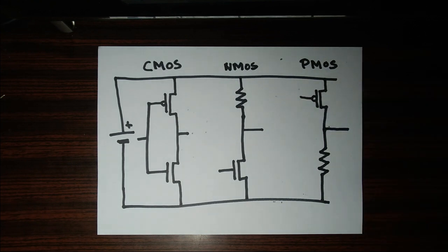Besides the disadvantages, NMOS and PMOS have a few advantages. One of these is that they require exactly half the amount of transistors of CMOS. Also, with NMOS, we can create a quick and dirty voltage shifter. This might be beneficial to those who want to connect an output of a microcontroller pin to a part of a circuit that works on different voltages.